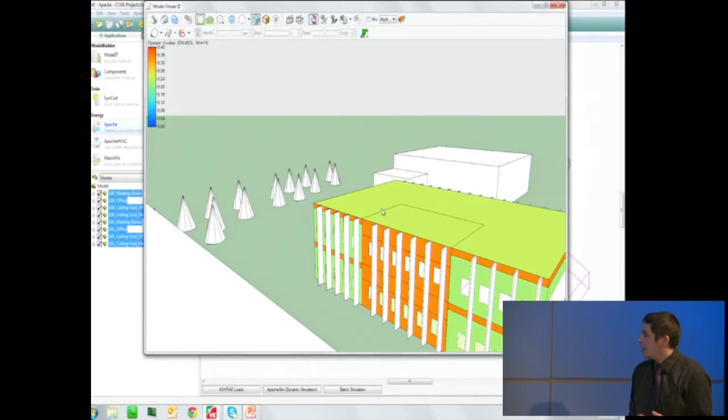So again, if I find I was perhaps failing or wanted to improve the performance of my building, and I was maybe wanting to address the fabric, I could open up this view and then quickly assess which constructions, which areas are the key areas to target first. Because I probably want to target the areas with the poorest U values, improve those areas rather than tackle areas which are already fairly good.